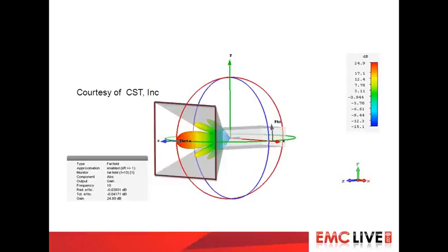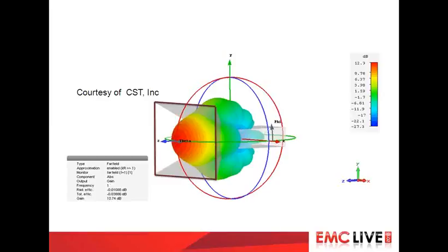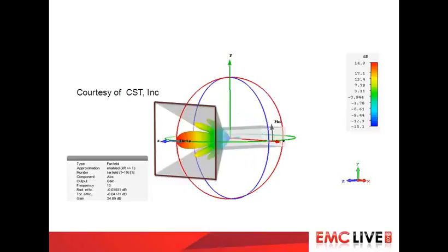Now, this is a webinar, so I'm not sure how soon your screens refresh. But I'm going to go back up to the original 1 gigahertz data, count to 4 seconds, and come down again, and hopefully it won't look too messy on your end. Going back to the first one, look how big the lobe is. There it goes. I'll give it 1, 2, 3, 4. Hopefully yours is there. I'm now going back. 1, 2, 3, 4. Hopefully you saw the trade-off there with this very poor antenna: you've got a tremendous gain improvement, however, at the cost of beam width.